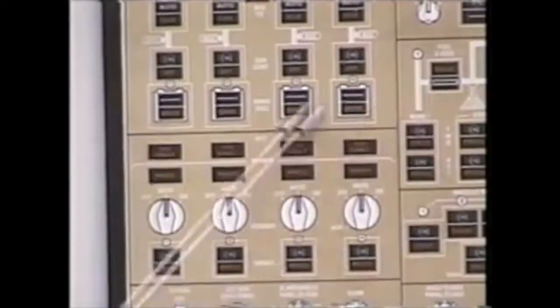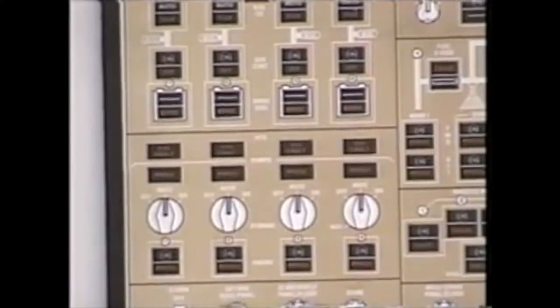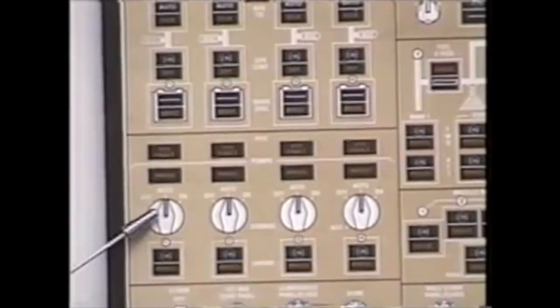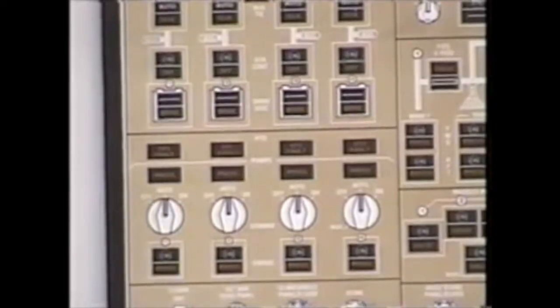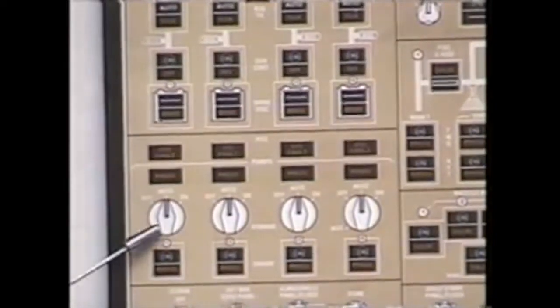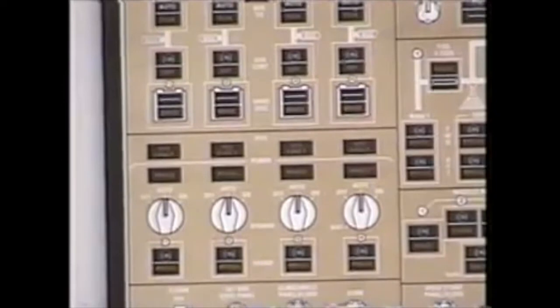Dropping down below the electrical panel is your hydraulic control panel. Hydraulic control panel, there are 4 separate totally independent hydraulic systems referred to as system 1, 2, 3, and 4. Each system has 2 pumps which can pressurize it, an air demand pump and an engine-driven pump. Air demand pump referred to as ADPs, engine-driven pump referred to as EDPs. Air demand pumps take pneumatic air from your pneumatic system to operate. Air demand pumps are 3-position switches, off, auto, and on.